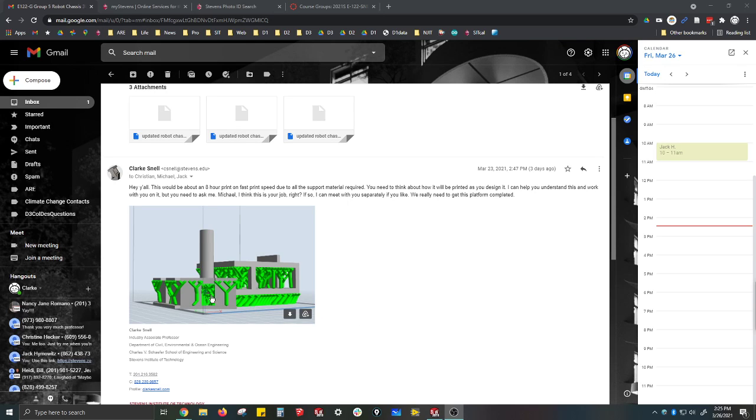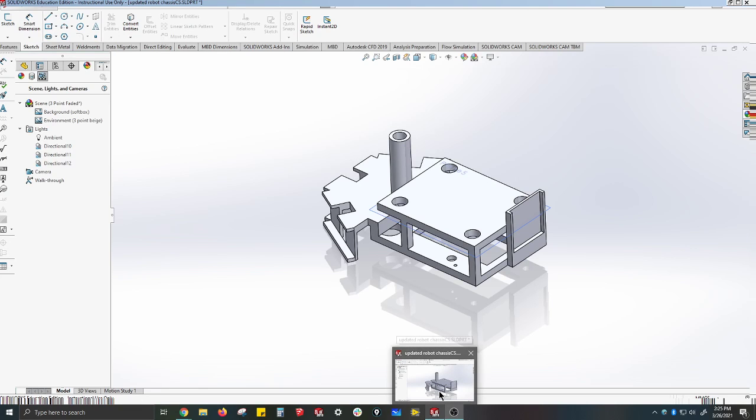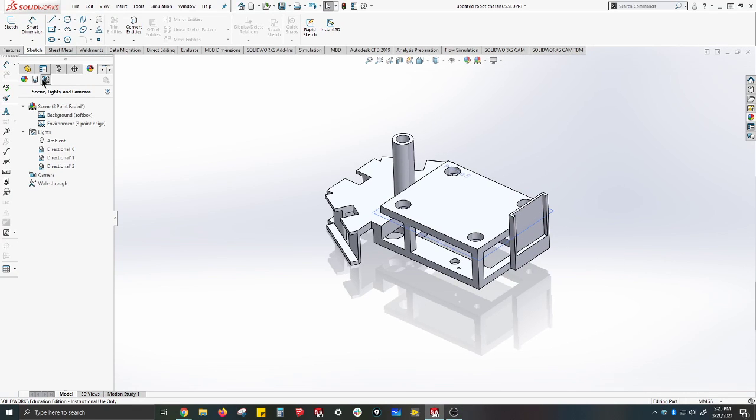So the problem is right now that we have a bunch of elevations in our one 3D printed part that require a ton of support material. Down beneath here, and this in here would be really difficult to get out. We might break these posts, and plus it's just taking, like we said, 9 hours, so it's not possible to do that in the context of this class. And it's actually bad design in terms of 3D printing. So let's look at your part.